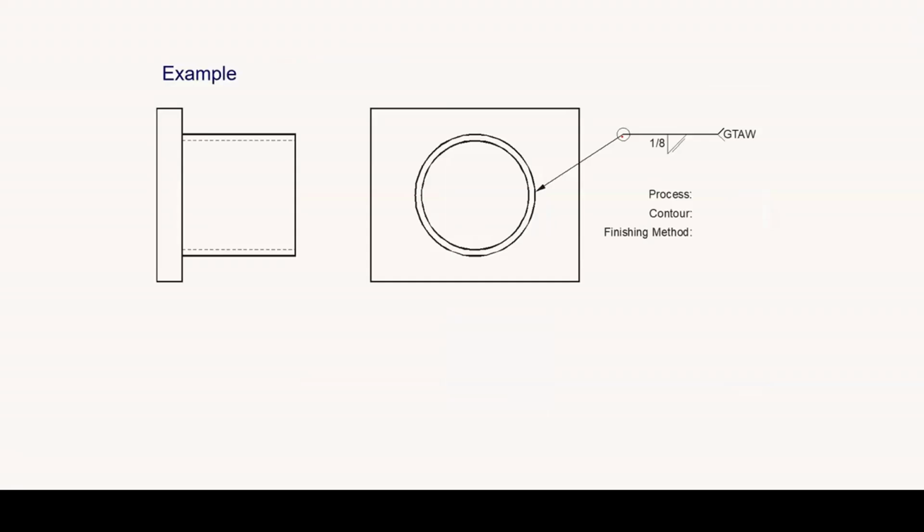And here comes an example. This will be given in your engineering drawing. You can see the weld symbol. We have a reference line, an arrow line, and also the fillet symbol, and this is the additional information, GTAW, gas tungsten arc welding. And also we have a weld-all-around symbol, so it is supposed to be welded on all the surfaces.